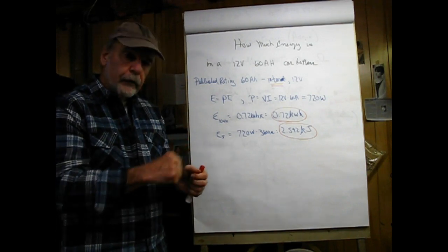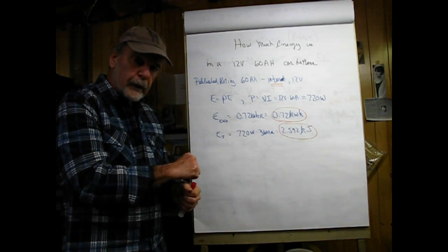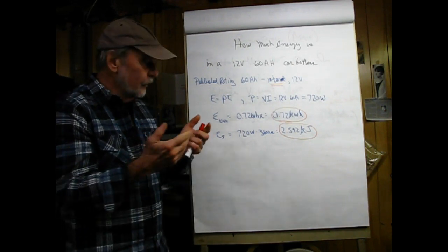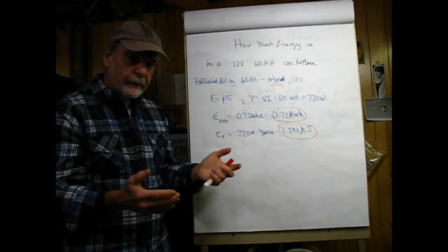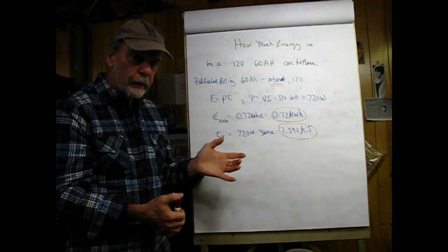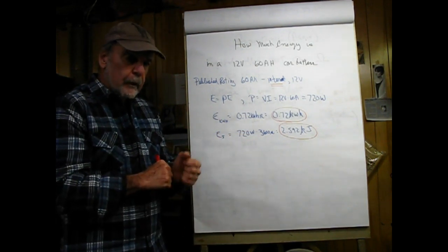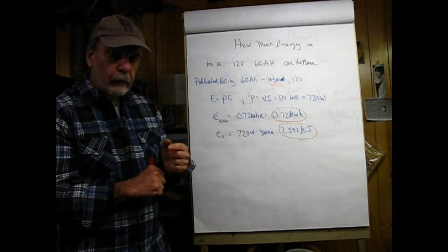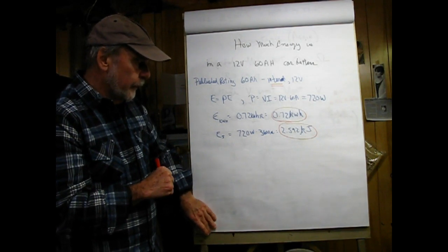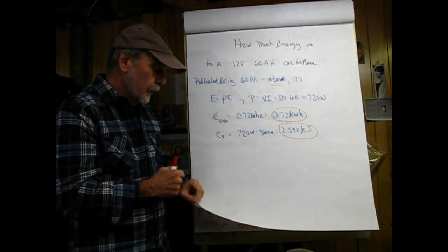On the other hand, if you're taking the positive off first, and it hits the frame of the car as you move the wrench around, you've got a short circuit across a very, very energetic power source. Even if the battery is partially discharged, it can really hurt you. So you take the negative terminal off first, and you put the negative terminal on last. It's the safest way to deal with a car battery. It's not the voltage, it's the energy storage capability, which is dangerous.